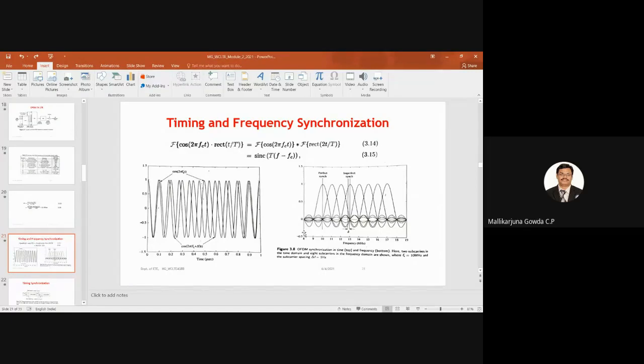Possibly to avoid interference. Yeah, that is one thing. To demodulate the OFDM signals. Yes, in order to demodulate an OFDM signal, these are the two important tasks which need to be performed. One is timing synchronization, another is frequency synchronization, as you said, and one of your friends said avoiding interference. That is also correct. So here two things are there: one is the timing offset of the symbol and the optimal timing instance. These two things need to be determined for timing synchronization.